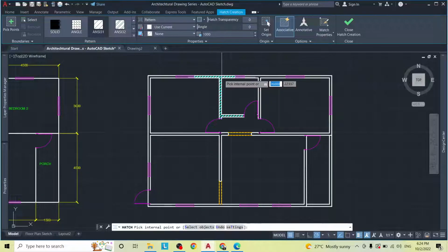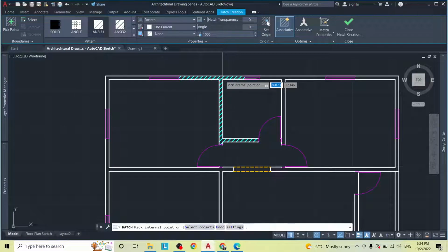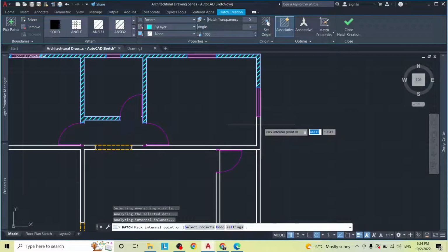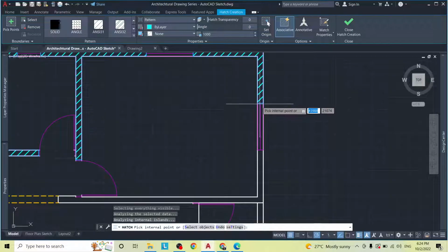That is better. All right. I'll probably have to reduce the thickness of these lines a little bit, so we'll do it after. We'll go to all of these wall points and just drop the hatch in. Do not turn off your window layer because you need them to be on, because the hatch is going to stop wherever it meets an obstruction.